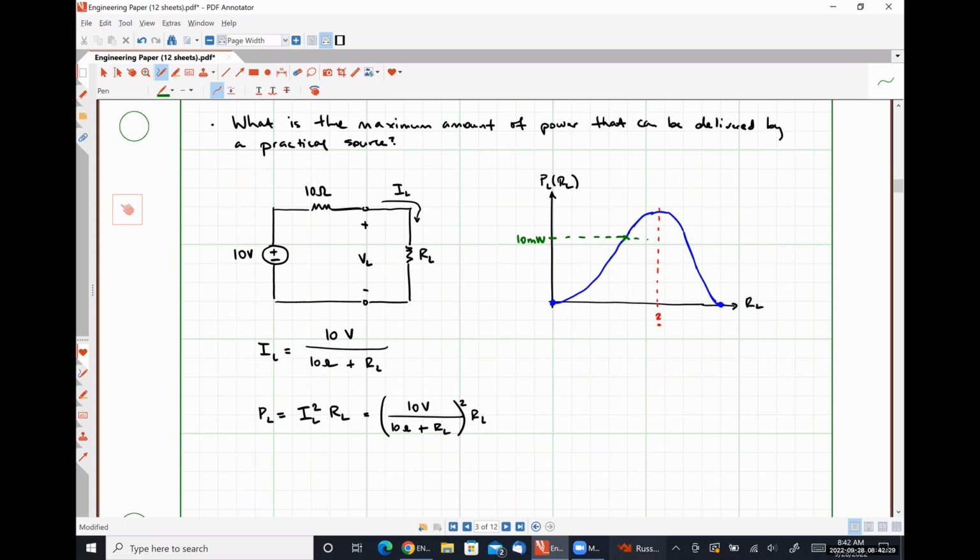There are actually two resistances that satisfy this constraint, one of which will be below the maximum power transfer point, and one of which will be above it. I am pointing this out to you because you're asked questions like that in your homework. This is a simple quadratic function that I expect you to be able to solve for the two roots that satisfy that power relationship, okay? So this is effectively the system that we are dealing with.